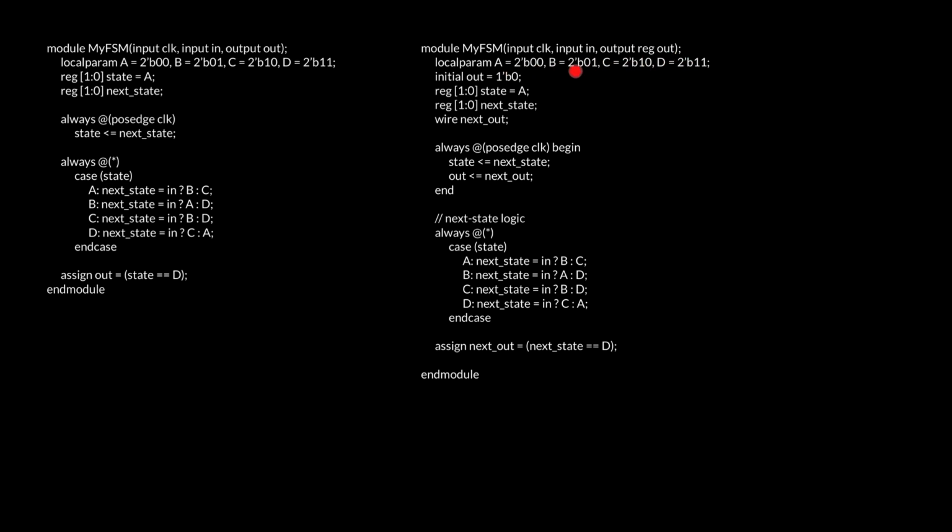In this case, I don't think we can, but in some other cases, that may be possible. Such a reduction has got nothing to do with the state diagram. The state diagrams are identical. It's simply choosing a state representation such that the output is simply a subset of the bits making up the full state. That's how you eliminate any potential for glitches on the output.